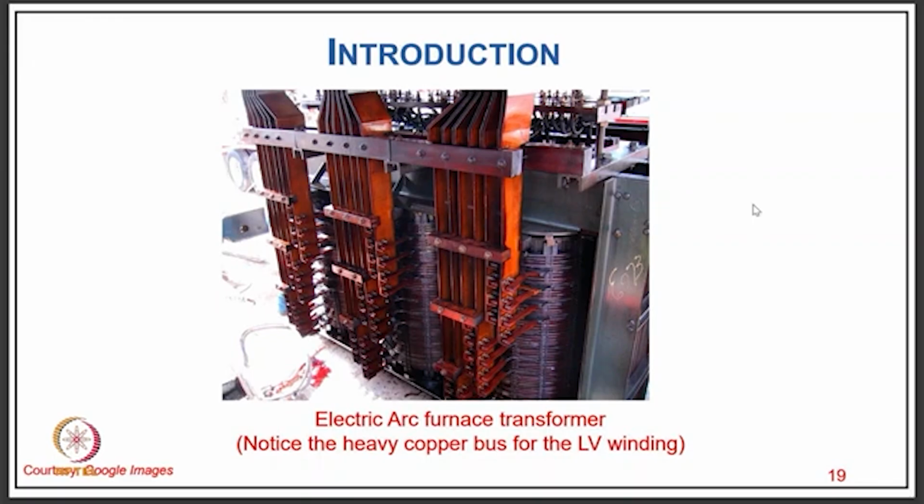or even lower than that, such a large single phase load we cannot connect directly to the three-phase supply system. So certainly we have a special arrangement of these furnace transformers for this purpose. The purpose of those transformers is number one, isolation, and number two, to convert this supply from three-phase to single phase. But when both the furnaces have almost equal load, it behaves as a balanced load on the three-phase supply system through this transformer arrangement.